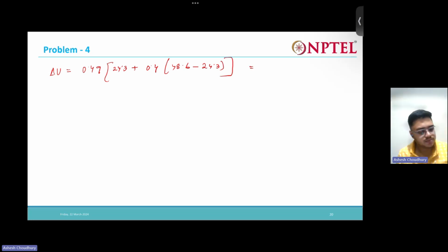To calculate this, calculate the increase in pore water pressure due to the increase in that extra loading, or due to the increment of that height, this extra pore water pressure is getting generated, right? So the extra 3 meter that you are building, you are raising the height of the embankment by 3 meters. So with the extra raising of height, you are generating some extra pore water pressure. So that pore water pressure is this. So calculate this, please.